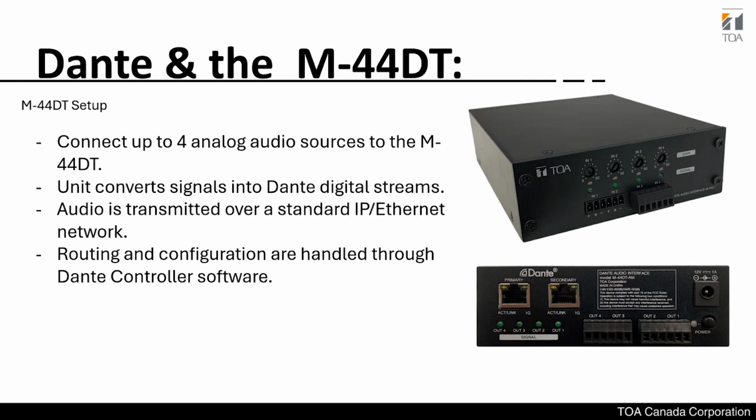So you connect up to 4 analog audio sources to the M44DT, and the unit converts the signal into Dante digital streaming. Audio is transmitted over the standard IP network, so we don't need any third party or any specific network switch. Whatever switch we have existing there, the Dante system will work with that. And the routing and configuration are handled through a single piece of software, the Dante Controller software.